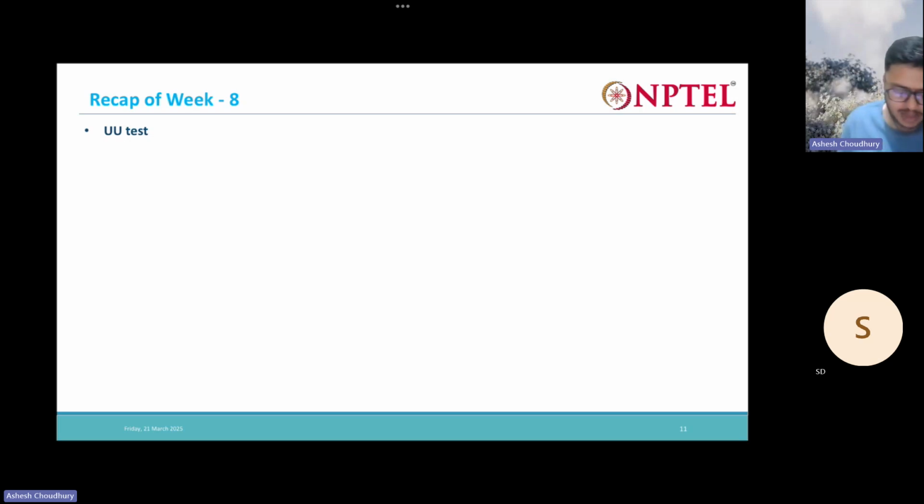So in the UU test, the unconsolidated undrained test, in the consolidation stage my drainage valve is closed, as well as in my shearing stage. That is, you are not allowing the drainage to happen. That is, no volume changes.